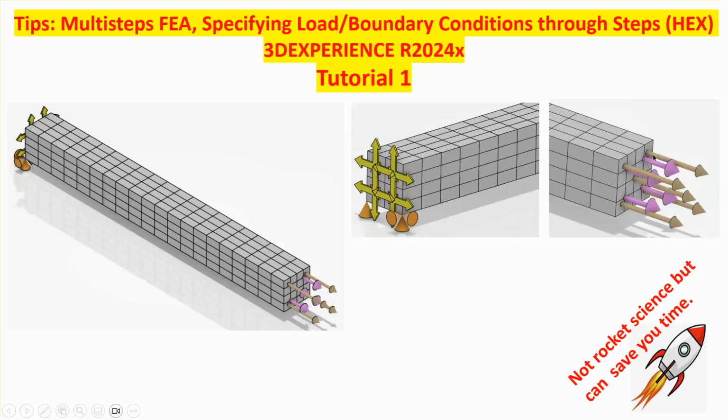On the right side, in these tutorials, I will either apply a pressure or a displacement or both, as you'll see. It's assumed that the dimension is 10 inches long, with a 1 by 1 square cross section, Young's modulus 30 times 10 to the 6 psi, 30 million essentially, and Poisson ratio 0.3.